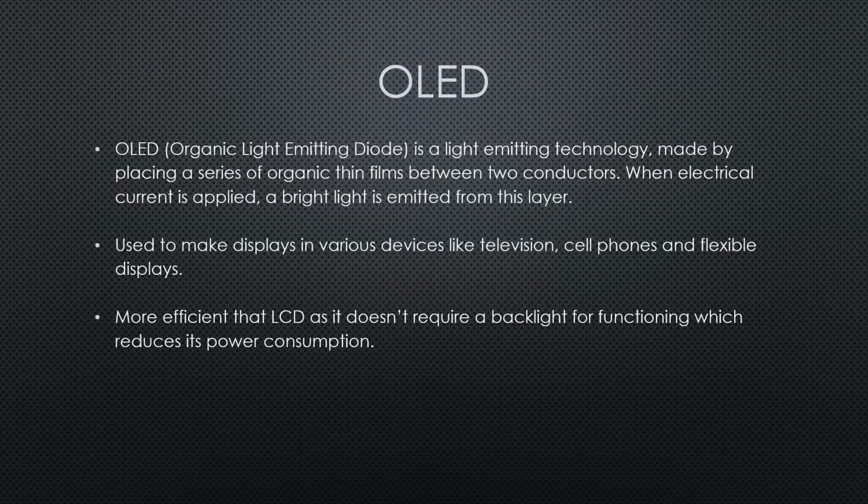So let's start with the introduction about OLED. What is OLED? OLED is a light emitting technology made by placing a series of organic thin films between two conductors. When electrical current is applied, a bright light is emitted from this layer. Moreover, it is used to make displays in various devices like television, cell phones and flexible displays. It is much more efficient than LCD as it doesn't require a backlight for functioning, which reduces its power consumption.